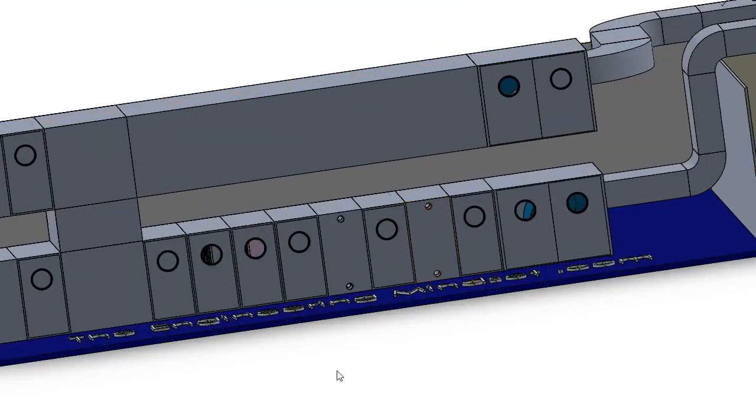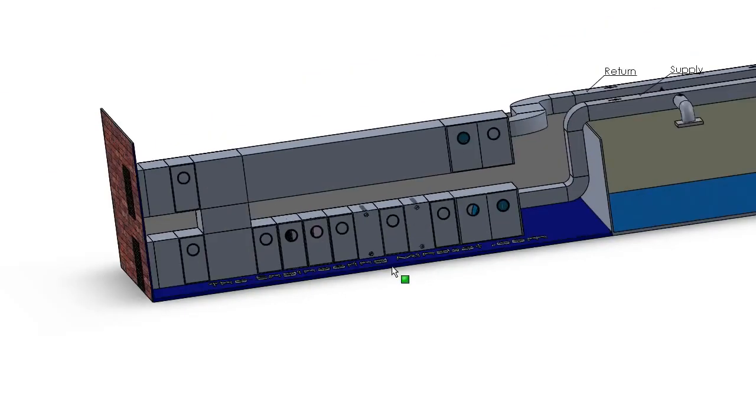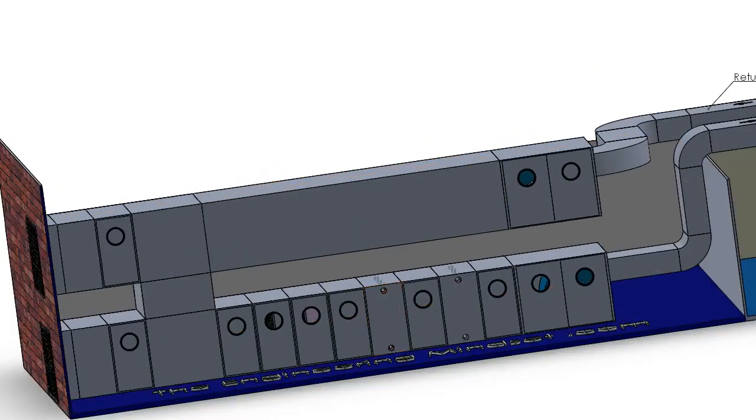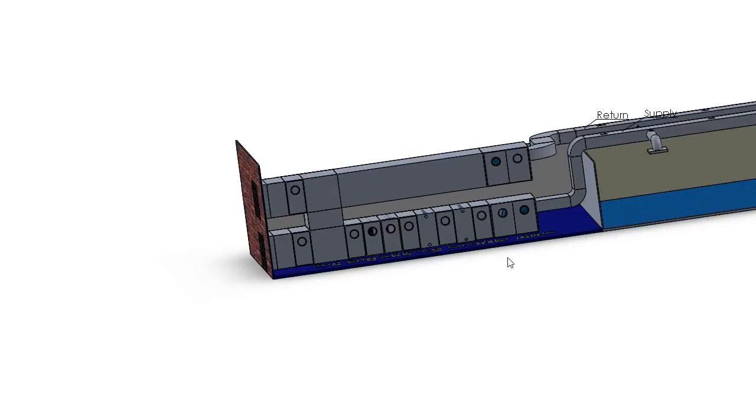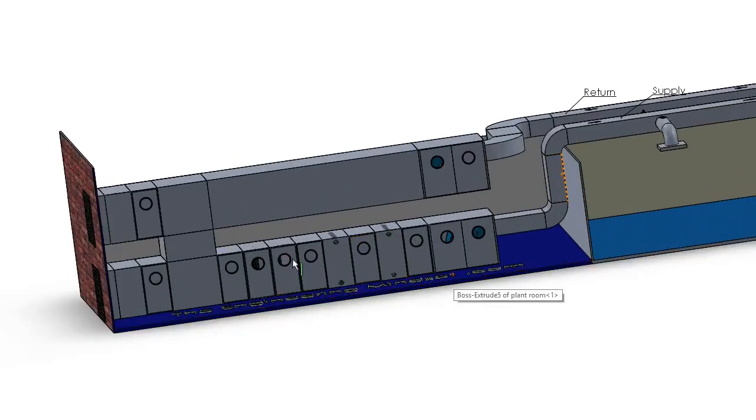So let's go back to the AHU. Position that a bit better. The supply air will enter into here. It's being sucked in, and there's a fan in here, and we're going to look at all these components one by one, don't worry. We'll just go through and make sure you understand what the system is doing first. So once that air has been pulled into the AHU, it passes through here, which is the HVAC parts inside, and that then gets pushed into the ductwork and sent off around the building.